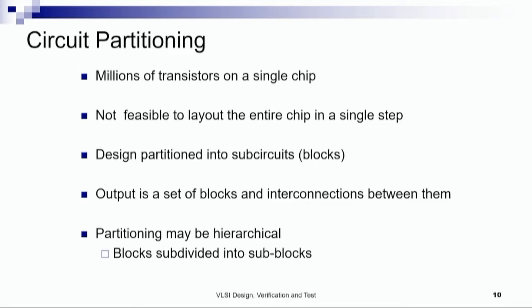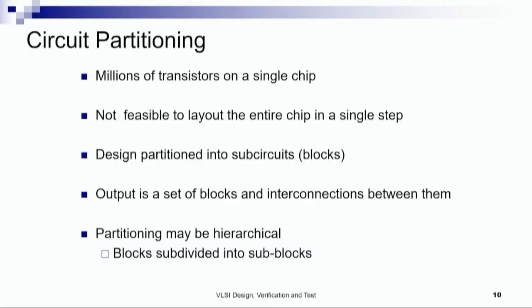So we have millions of transistors on a single chip, and it is not feasible to lay out the entire chip in a single step. Hence, to control the complexity of the design process, we partition the circuit into sub-circuits or blocks. The output is a set of blocks and interconnections among them. Partitioning can be hierarchical, blocks can be divided into sub-blocks.